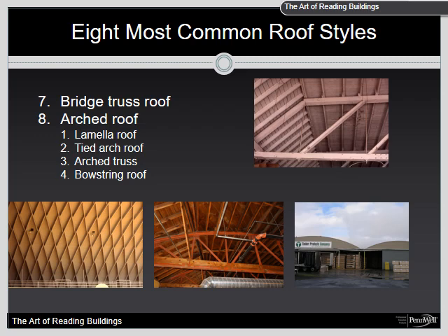More likely, failure of any part of the roof can precipitate a total roof failure, depending on the type of fire. Compared to other arch roofs, the tied arch roof can offer significantly less structural integrity during fire conditions and should be considered very dangerous. Consider also the age of these roofs, and this leads to multiple layers of composition roofing material.